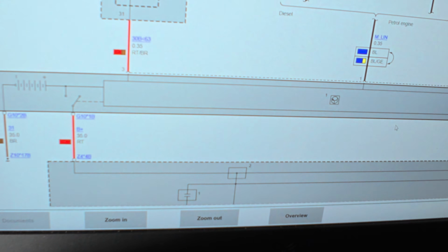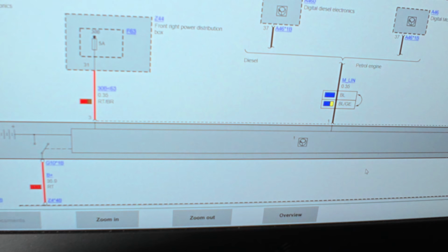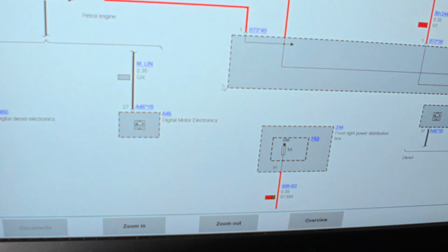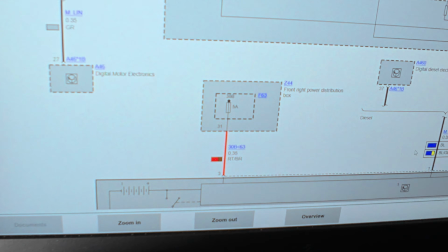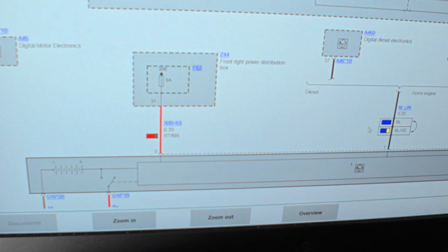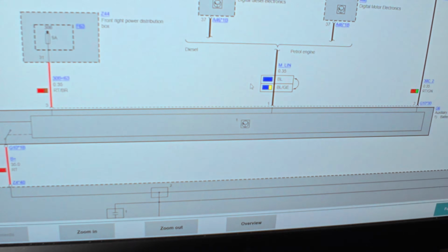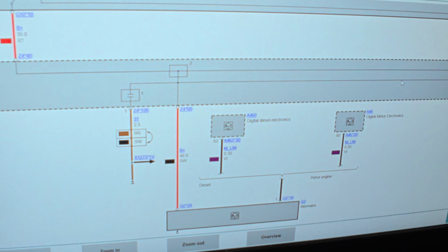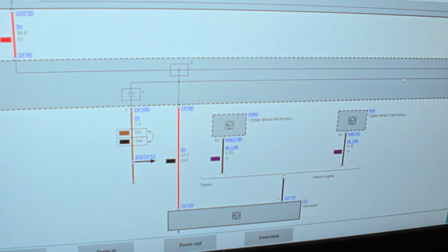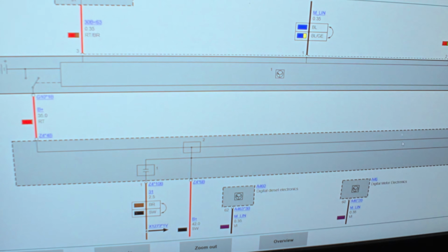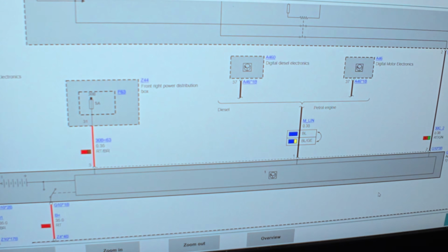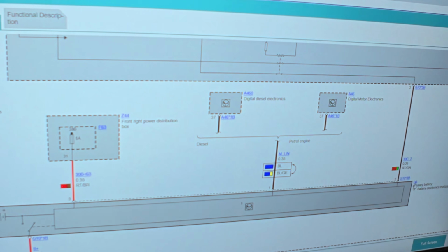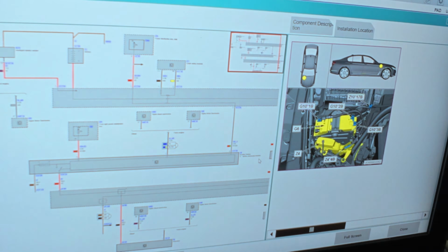So this is the battery electronics module, G6, and it's on the LIN bus, but it's not on the gray wire LIN bus. It's on a different color. I don't understand how this thing could be affecting us if it's not on our gray wire LIN bus. But neither is the alternator, but the alternator is on a LIN bus. So I suppose this is blue and beige.